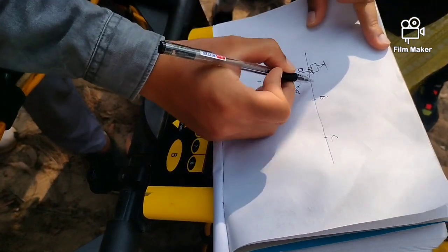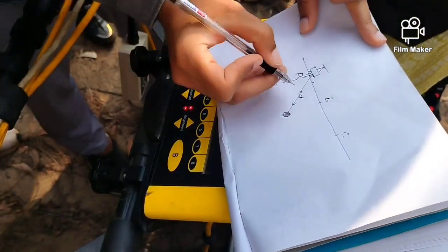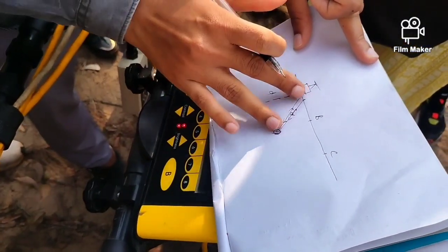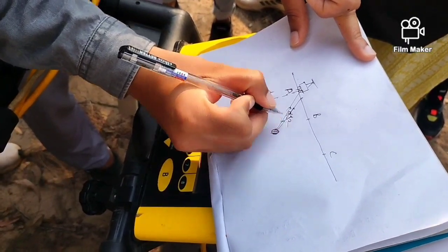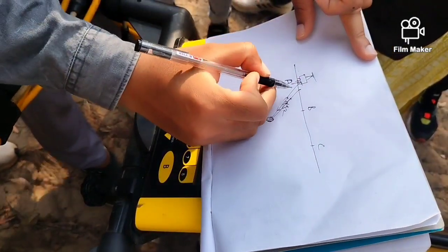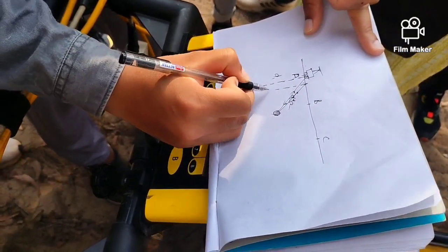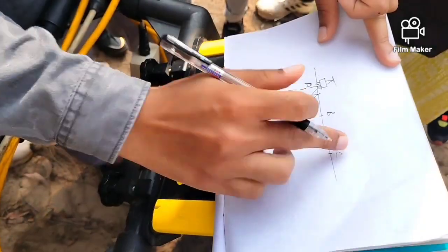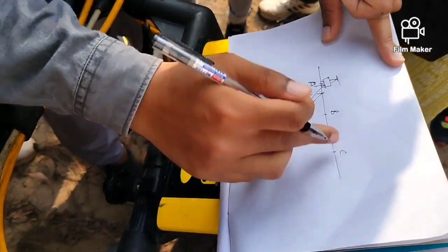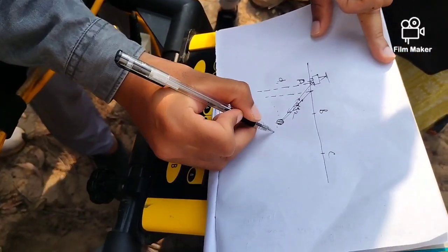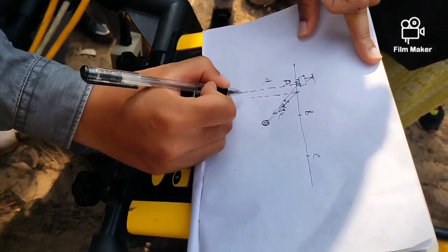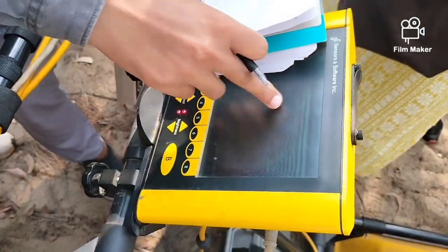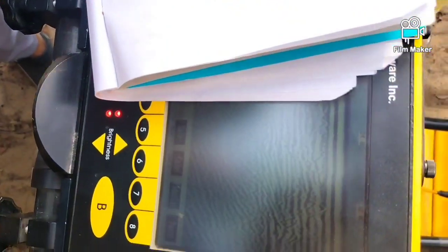Okay. Now the GPR will move here. So the frequency will go here and then come back here. Now this distance, which is D2, is smaller than D1, right? So at this point you would see that it is coming from this point. Similarly, it would go here, here, here as GPR is moving in this direction, and then as it's going away from here, it'll just come back like this. So the structure we would get is a hyperbola, and that's what you see here. So that's why you see a hyperbola when the point object is there in the subsurface condition.